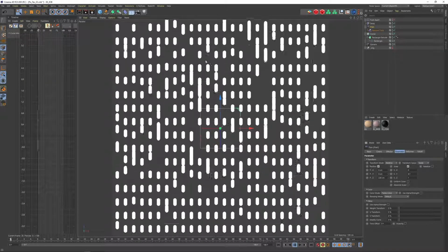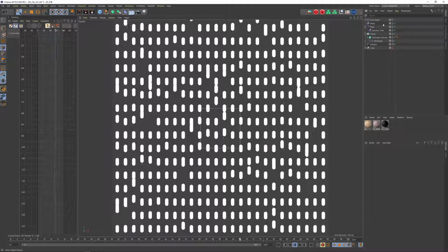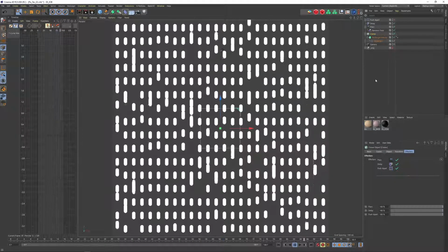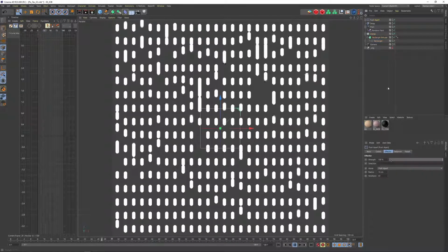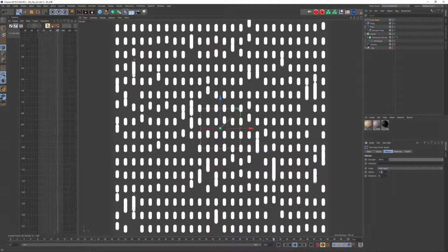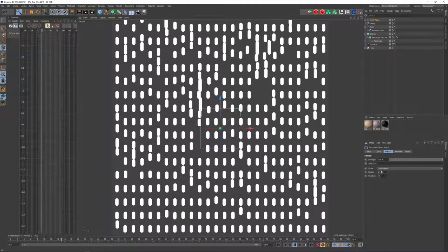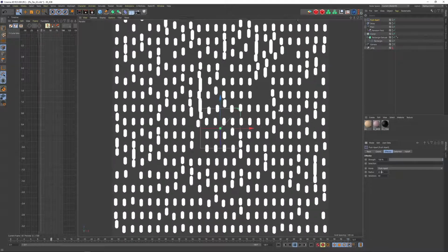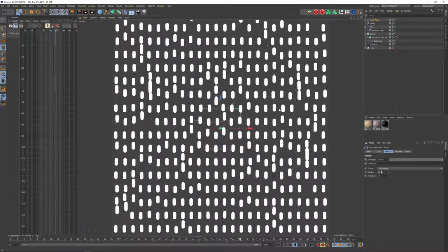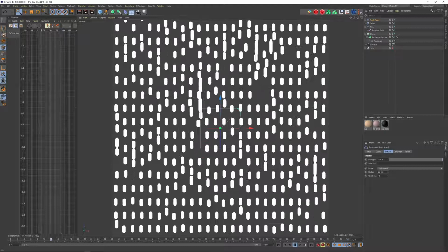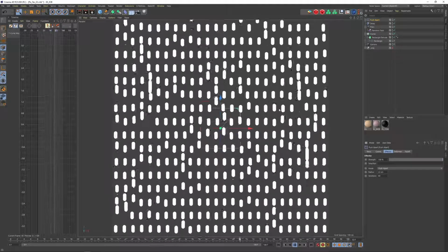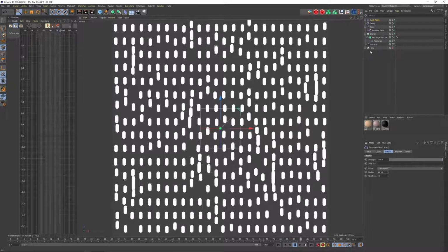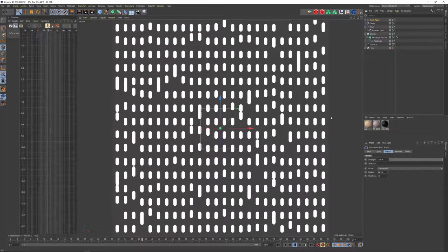Then this was already everything I made and rendered, but just a quick thing, you can also apply the push apart effector at the end of everything, and then something like that happens. Well, first of all I have to increase the effect a bit stronger, let's say like 20, and now they try to avoid intersecting, and I think this also looks very interesting. But for now, I didn't use it because I wanted a more clean texture, not too much noise, just to have it clean. So nice, I then deactivated it and I have the cleaner version.